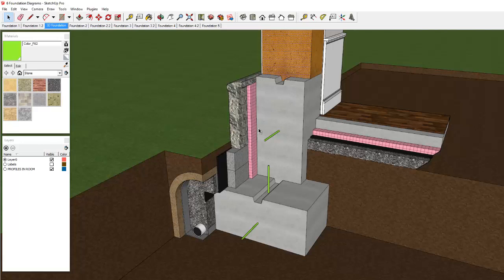Okay, so foundation, I won't get into every detail here in this video, but you'll see some drainage. There's different ways you can do the drainage around your foundation or even underneath your foundation, but this is to keep water away from the foundation, from wicking up through the foundation and into the cob or earth wall.